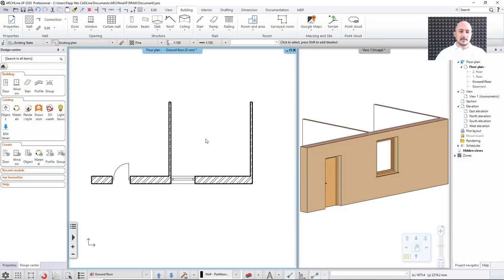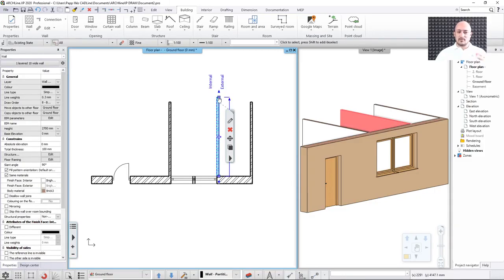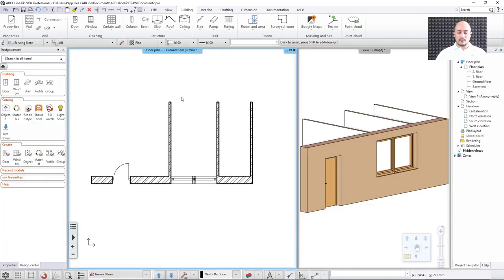Now actually, for this reason, to be able to make changes easily and compare the different phases, there is also an all phase here, which, as you can see, makes all the phases visible, so I can make decisions whether this was okay or not. This should be moved to somewhere else. And for example, I just created this wall, but I would like to make it similar with the other two in length. So I change the length and make them align to the other one. So this is why the all design phase filter is good. And then now I can go back and make it simple to see only one of the phases.